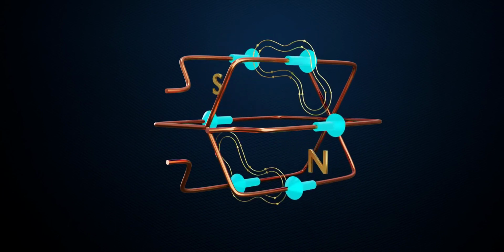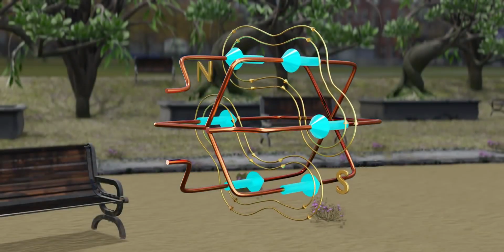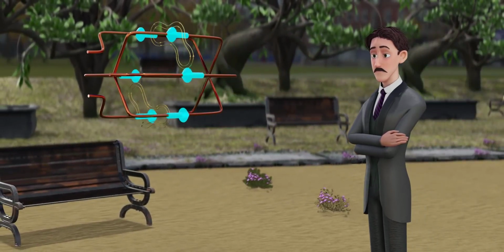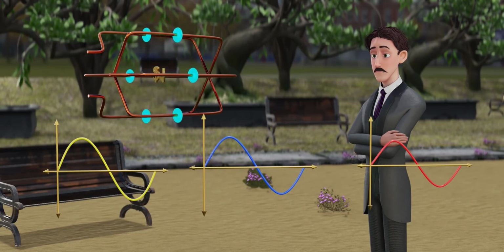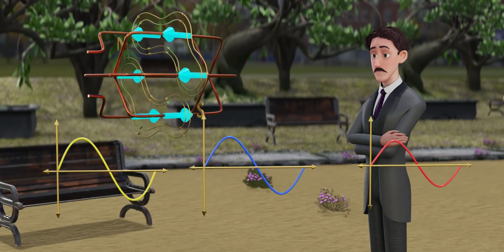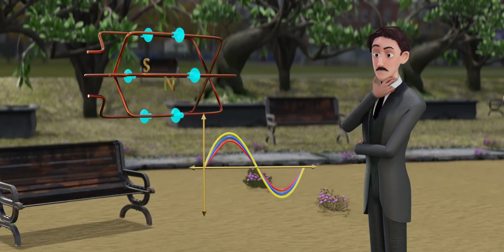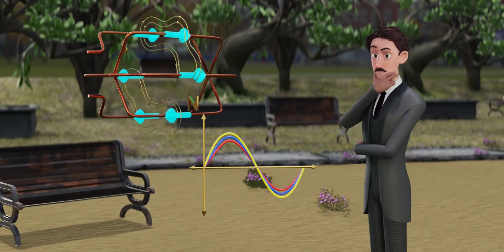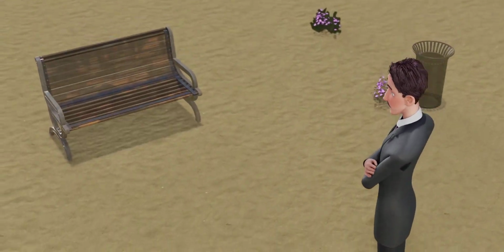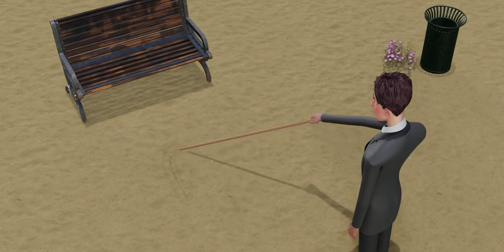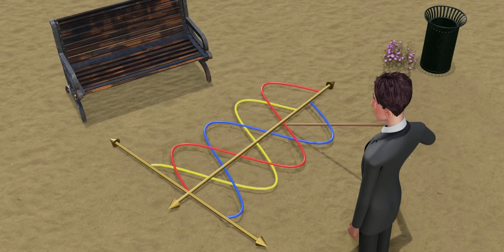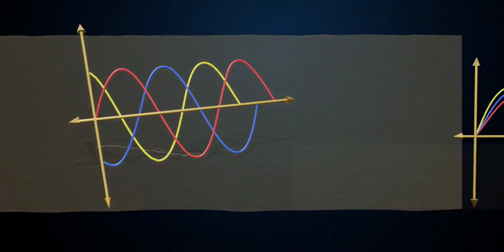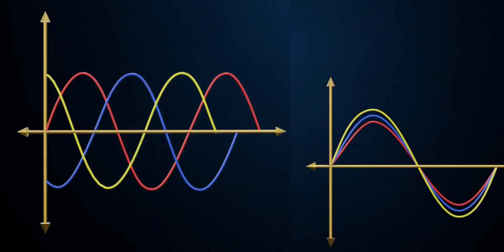This is where one of the godfathers of electrical engineering, Nikola Tesla, comes into the picture. He observed this disappointing behavior of the magnetic field's fluctuation. This field fluctuation happens because all three fields, maximum or minimum, happen at the same instant. Tesla, while walking in a park brainstorming ideas to create rotating magnetic fields, wondered what if he keeps maximum values at these three fields at different instances? Then there will be no instant when all three currents are zero or maximum at the same time. Eventually, the resultant field will not become zero at any instant. In short, he can avoid the fluctuating behavior.